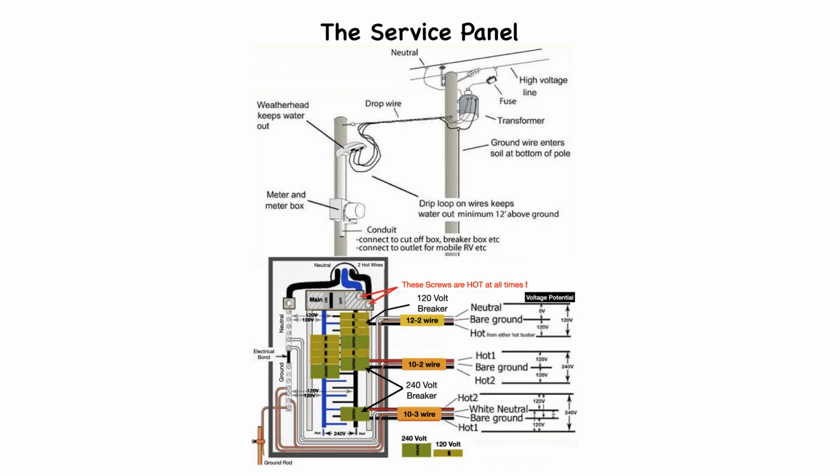The service connection enters the panel via the main disconnect breaker, which is utilized during emergencies or maintenance, to stop electrical power flow. This is positioned in between the service meter and the rest of the electrical panel. The main disconnect is a circuit breaker housed in the electrical panel.